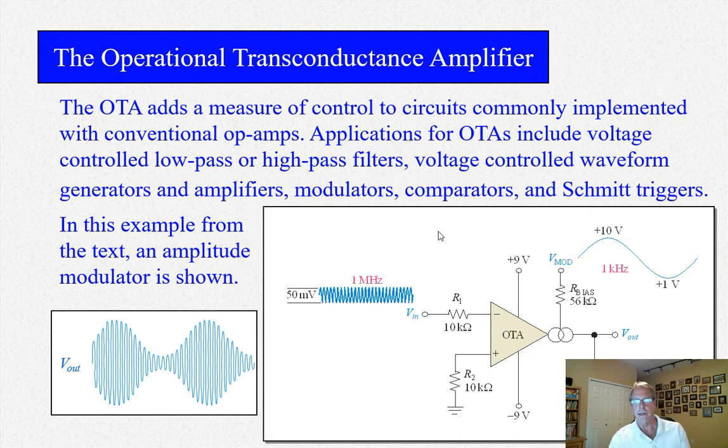So again, this is used a lot in amplitude modulators. It's also used in voltage controlled filters. Imagine connecting this output to a filter. We do filters at the end of this course, but a filter which produces a greater voltage at higher frequencies is going to cause this amplifier to boost those high frequencies as well. And if you do the inversion of that, it's going to be a low pass filter, in other words, a filter that attenuates high frequencies. Lots of different uses for this OTA.